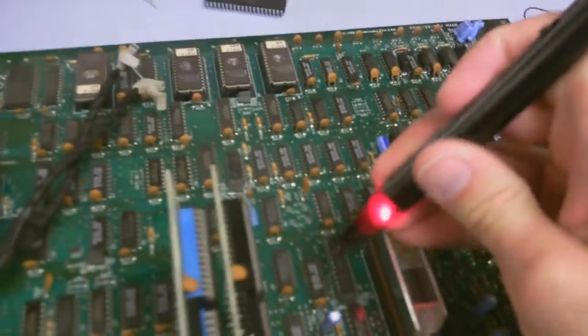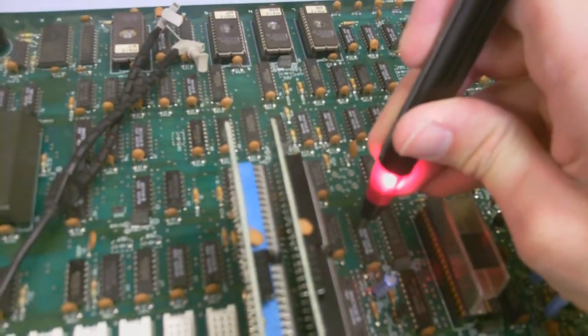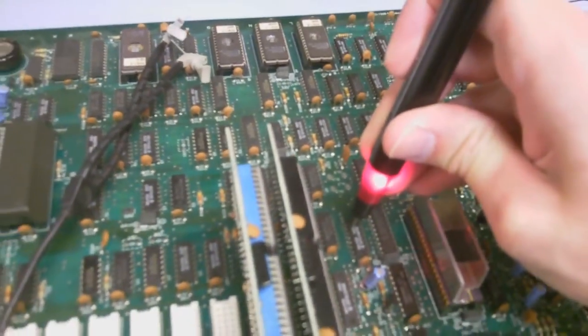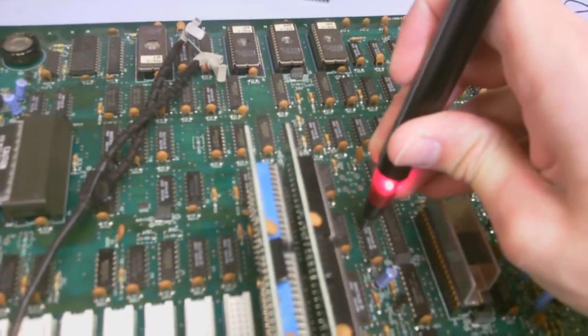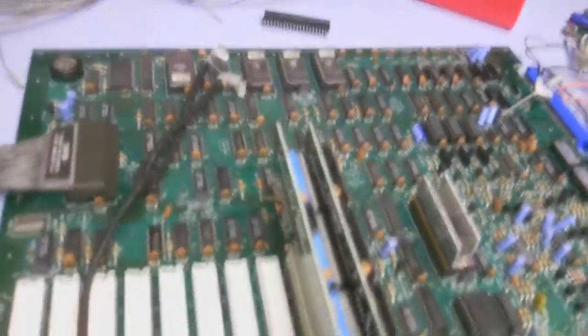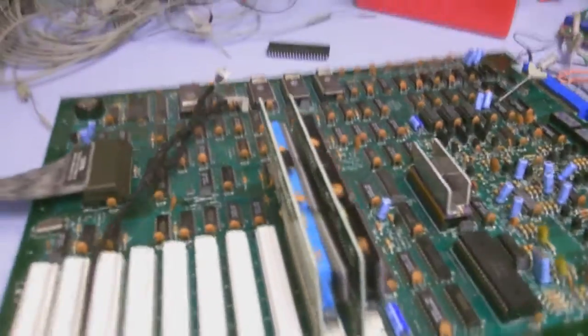Looking at the schematic, it comes from, looks like this guy right here, which is, let's see, 4L pin 11, which is right over here. So 8, 9, 10, 11. Now this guy's high. So that doesn't make sense, because this guy is high and this guy over here is low. And so I lifted the board up to see if there's something weird going on, and sure enough, what do we see? A bunch of hackery here.